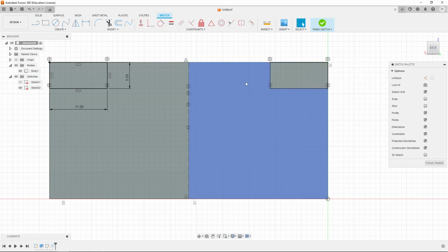Some things to note. The measurements don't come along because you don't need to duplicate measurements. And in fact, these constraints, the horizontal and vertical, also don't come along because the implication is if this is an exact mirror of this and these are vertical and these are constrained, then these must also be constrained. So there it is. We have our object, and these are the visual symbols for that mirror constraint. You can see there it is, the symmetry. This is what we're doing, which is really convenient.